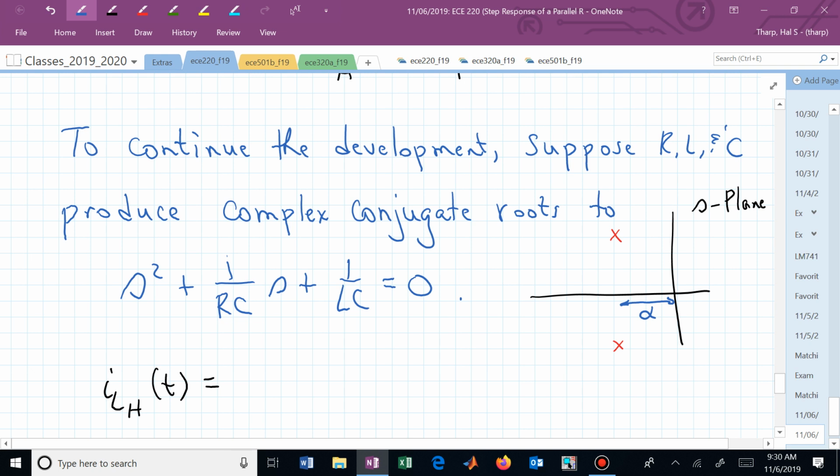How far away are they? What's their hypotenuse from the origin? That's their natural frequency, omega sub 0. And now if you remember this picture, you don't really have to remember the formulas, you just have to remember geometry and trig. Now, their damped frequency of oscillation, this distance, is omega sub d. That's the picture that you can envision when you're thinking about the solutions to this characteristic equation.